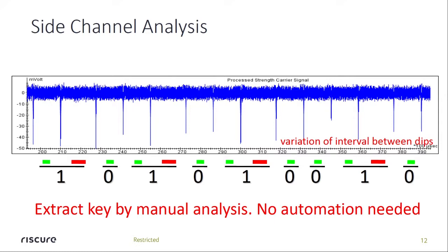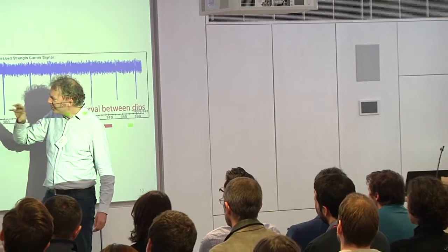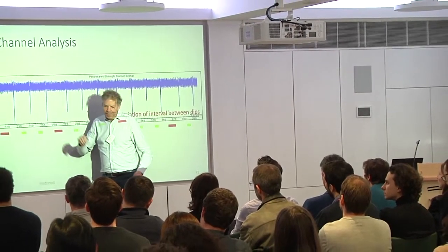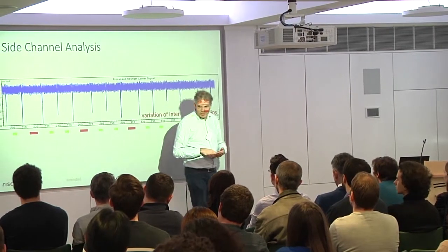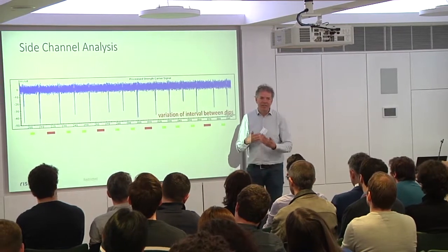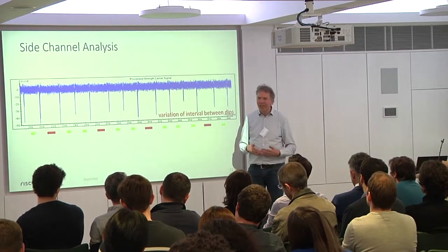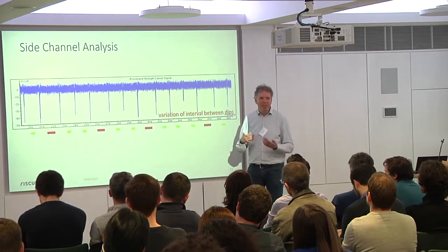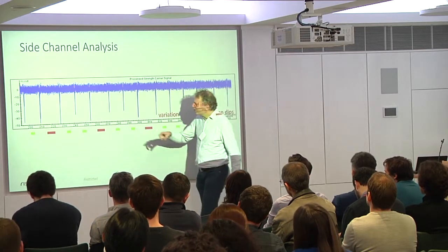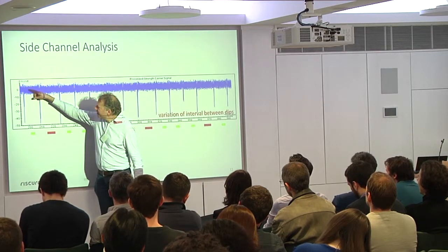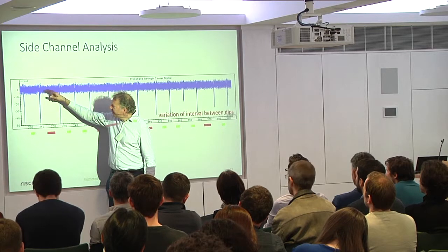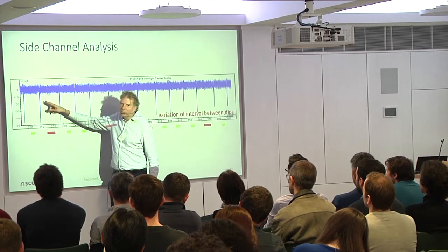And how can we understand this graph? So this is a chip that includes a hardware accelerator. So the hardware accelerator does the modular multiplications. These are multiplications on large numbers, so typically 1,000, 2,000 bits. So while it's doing the multiplication, it is using a lot of energy. And at some point it's done, and then it goes back to the normal CPU.